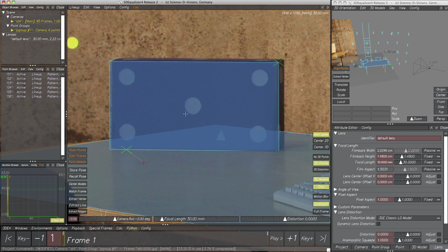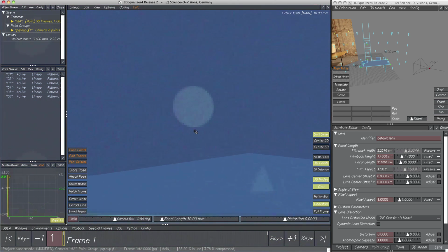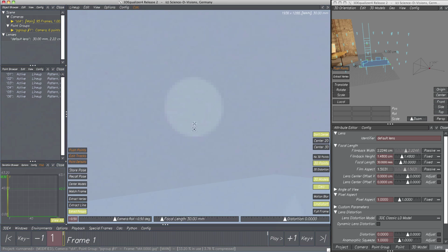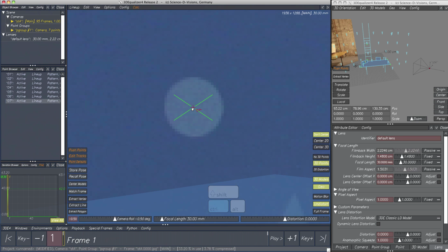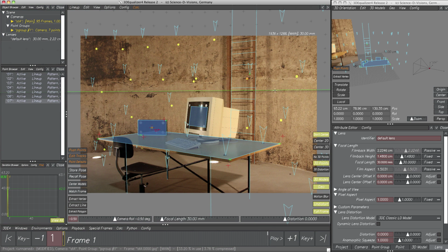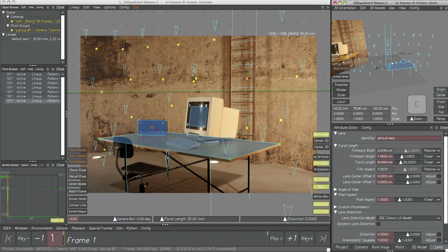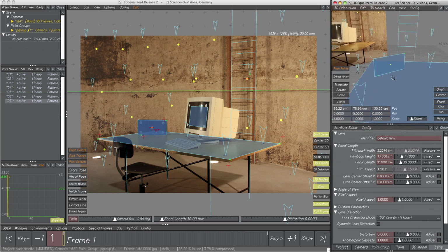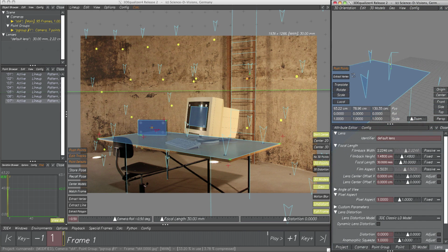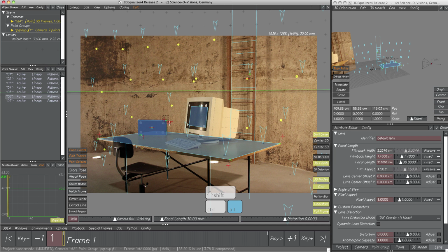So let's concentrate again on how to extract survey out of the polygon. Activate Extract Polygon and create a point in the center of the marker. As we can see, the 3D coordinates were extracted from this polygon and assigned to a 2D and 3D point. Since we don't need the other 2 points on the box anymore, we can delete them.